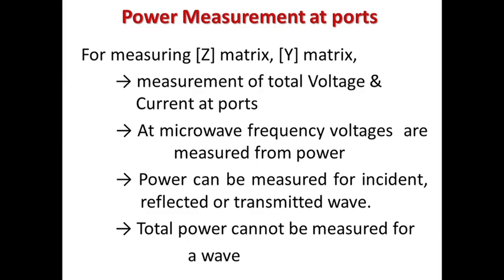That means we cannot say that incident power plus reflected power is equal to the total power, that is not true. Superposition principle is applied for voltages, but for power it is not. So, measurement of total power is difficult. That is why measurement of total port quantities at microwave frequency is a difficult job.